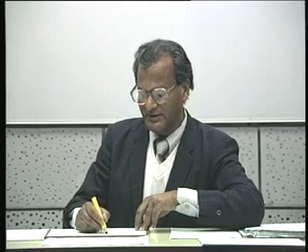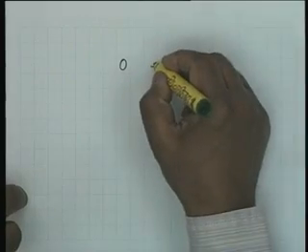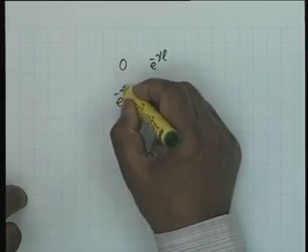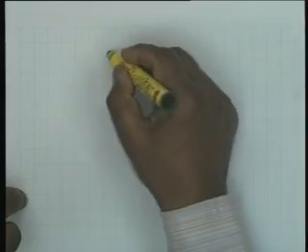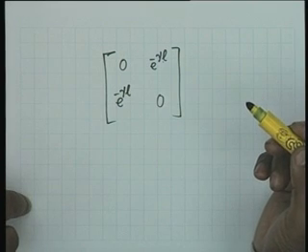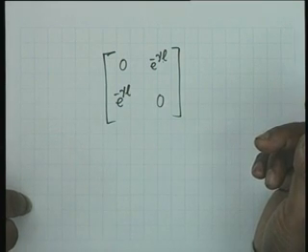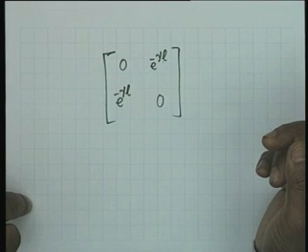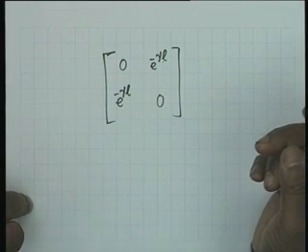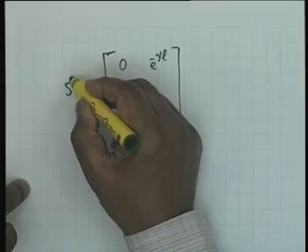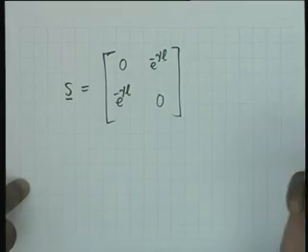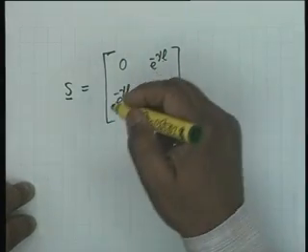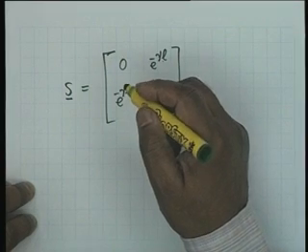Therefore, the scattering parameters of the transmission line terminated in characteristic impedance are 0, 0 diagonal elements, e to the minus gamma L, e to the minus gamma L. The equality of these two comes from reciprocity, and anything else? Just reciprocity. No, symmetry does not guarantee it, just reciprocity. So this is the scattering matrix. To denote that it's a matrix, I'll put a bar at the bottom. I'll underline the letter.